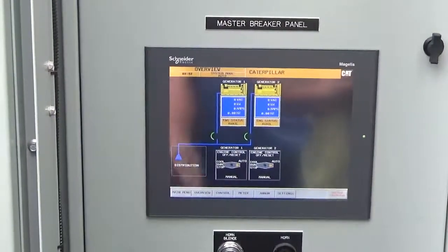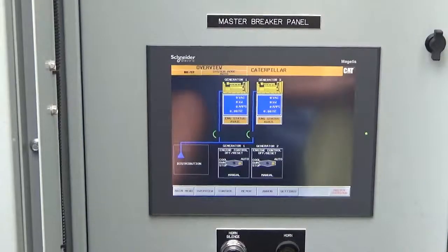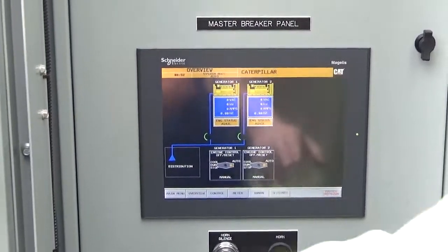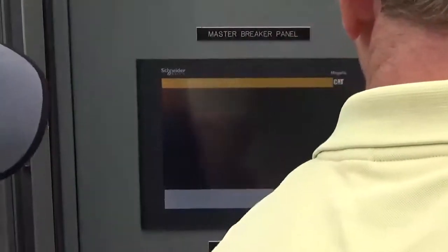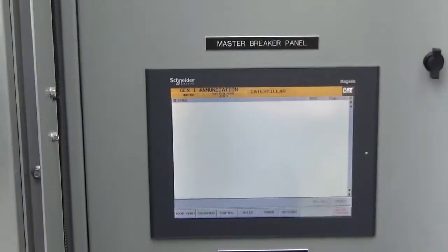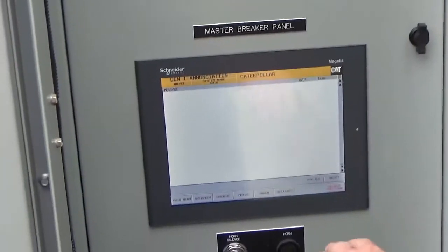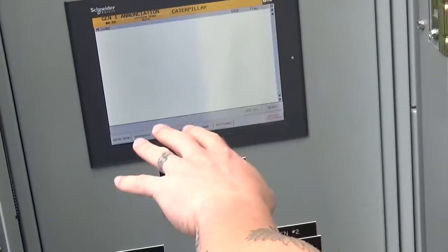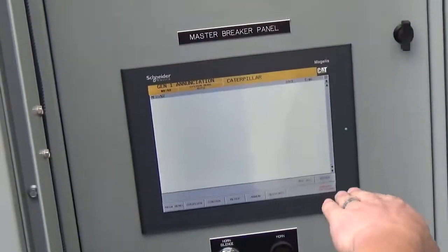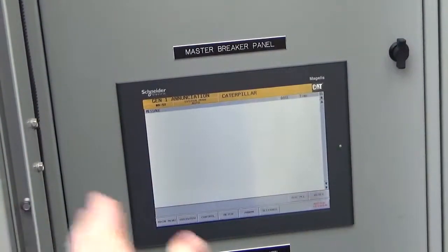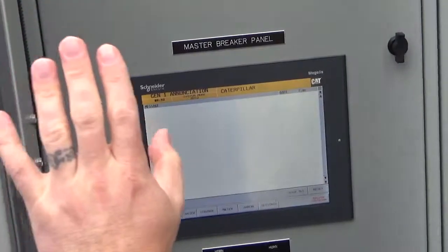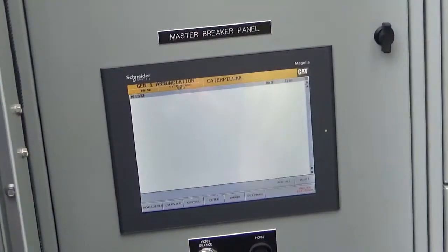But you'll see, we had this annunciator right here that was blinking solid red. And we had to acknowledge it, and once we acknowledged it, then it went away. So you acknowledge it, and then you can hit... Actually, a lot of times with the shutdowns, you have to hit reset. But if you acknowledge a pre-alarm, it goes away. Once you acknowledge it, you're done. Pre-alarms are done. With a shutdown, you don't have to.